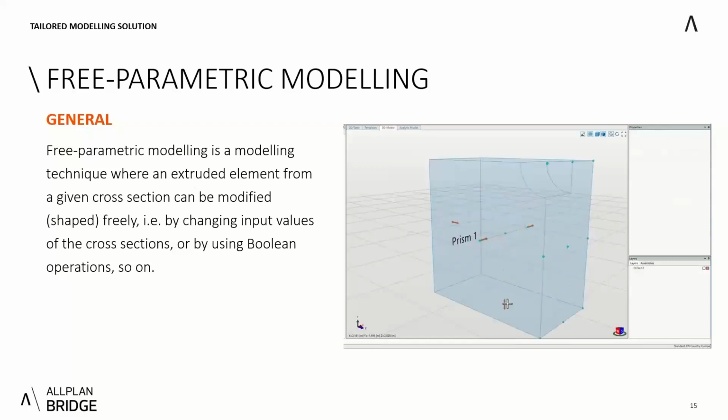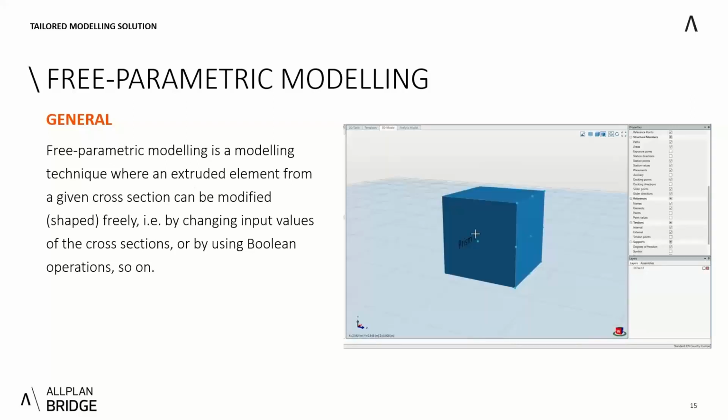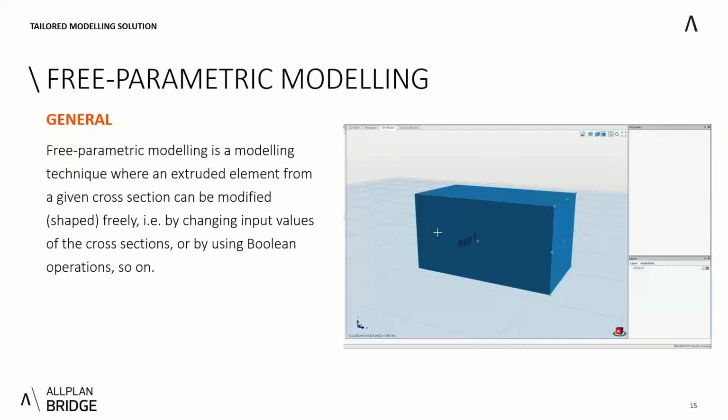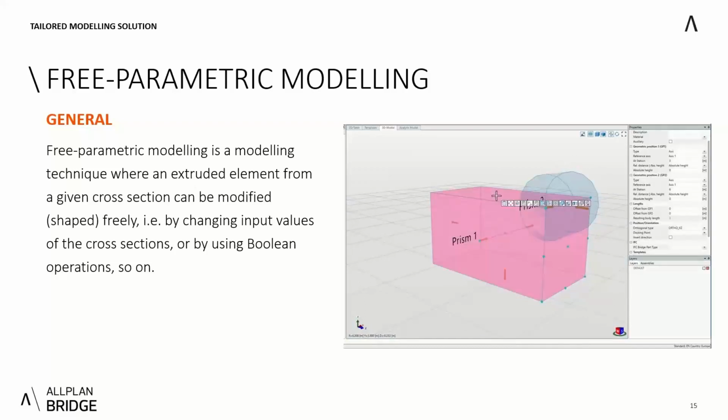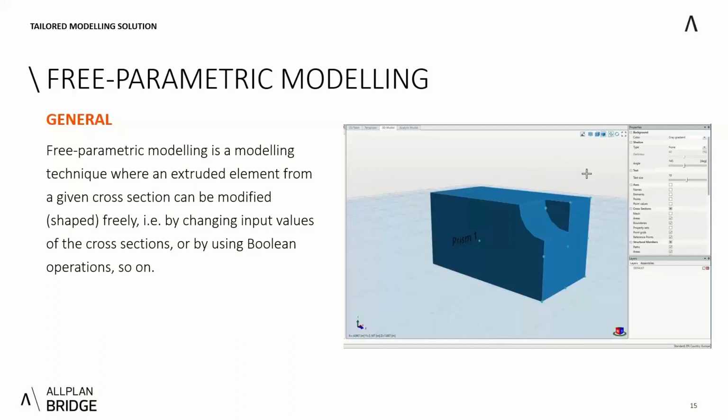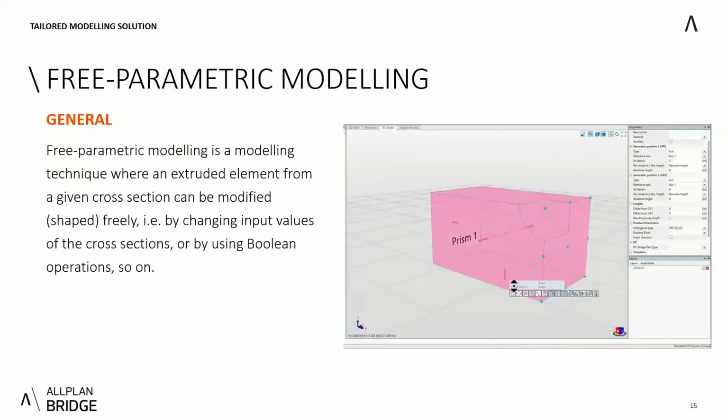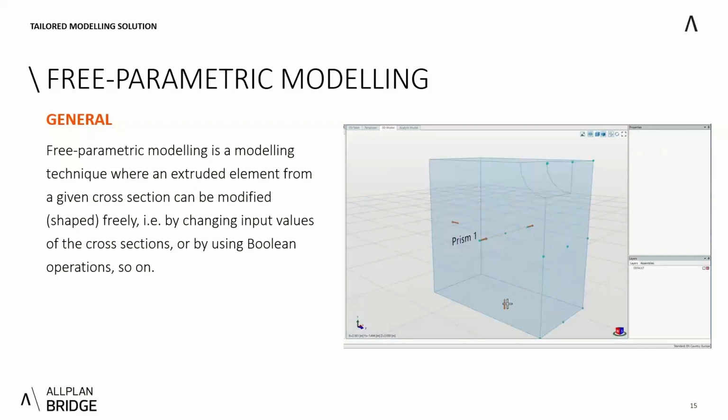Once we did that, we were able to modify the girder by changing the variations and adding variables. The objective is that you can introduce a change at any point, but the operations you did, such as the extrusion or the Boolean subtraction operation, will stay parametrically in relation to the object. For example, if you change the height, that operation will stay in that position. If you change the thickness, because we were doing it to half of the thickness of the shape, you can also see the subtraction of that shape to half of the thickness.